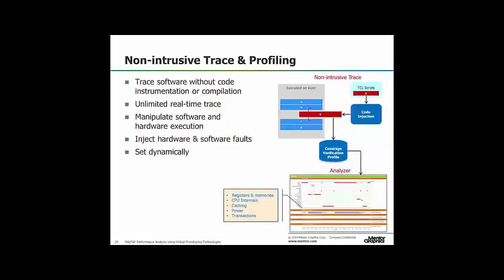And then a really powerful and great benefit of using virtual prototyping is that it gives us a chance to non-intrusively collect performance data. So we can trace and profile without any form of instrumentation. We don't have to recompile the software source code, so the results that we get from analysis are truly aligned with the release version of the software image.